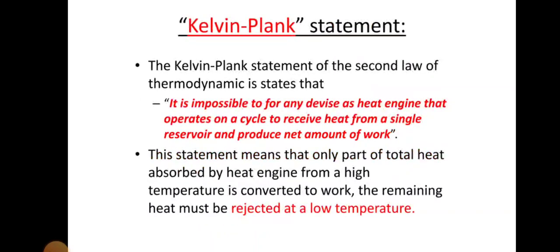The Kelvin-Planck statement of the second law of thermodynamics states that it is impossible for any device operating as a heat engine on a cycle to receive heat from a single reservoir and produce a net amount of work. This statement means that only part of the total heat absorbed by the heat engine from a high temperature source is converted into work. The remaining heat must be rejected at a low temperature.